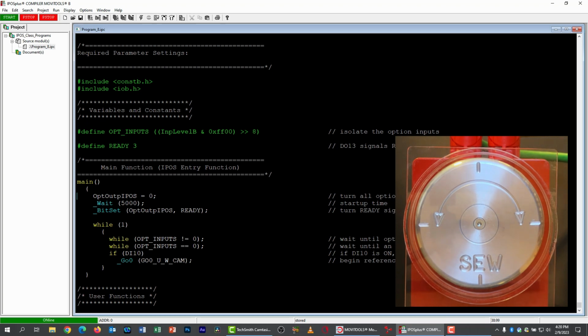Looks like everything worked, but remember we were supposed to explore what happens with our limit switches. So I'm going to trigger referencing again by turning DI10 back on. I did turn it off earlier. You can see now I'm referencing again. I'm going to turn my right limit switch off, DI04, and that tripped a fault. I will flip that switch back on and reset my VFD by toggling DI07 to clear that.